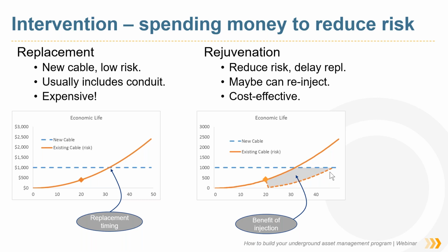And that gives us two benefits. One benefit is that we get lower risk for the next 40 years because we've addressed the cable. And the other benefit is we get to delay the high cost of cable replacement for 40 years or some number like that. And so your asset management approach should consider those trade-offs between capital spending, avoided risk, and delaying of capital expenditures when you're coming up to time to make a decision about what your strategy is going to be.